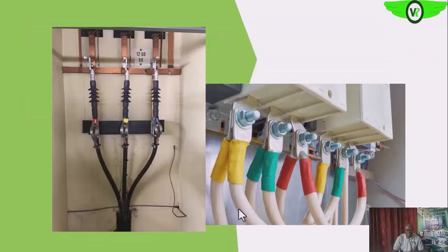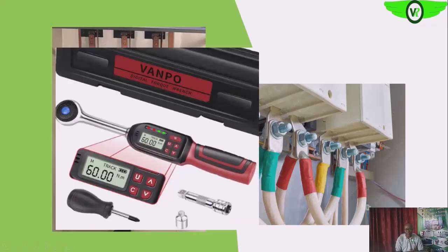So the next thing that we want to do is to check these terminals, that they have the required pressure, okay, the required torque level. The bolts on these terminals are torqued to the required level. So you need a torque wrench for this, okay, a calibrated torque wrench.